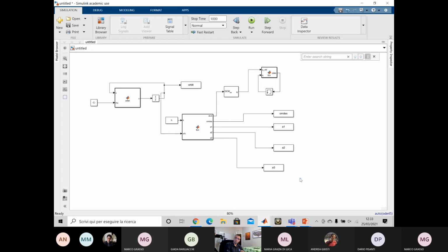the conversion from inertial to body, right? Yes. So what I suggest is you take what you've already done, assuming you've completed homework 1, the block that simulates the dynamics and the quaternions, and you take that quaternion to put together the rotation matrix to apply to omega. Make sense? Sorry, no, I didn't understand.